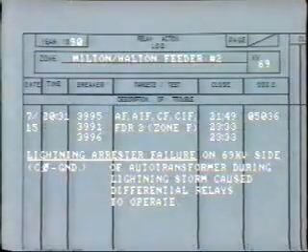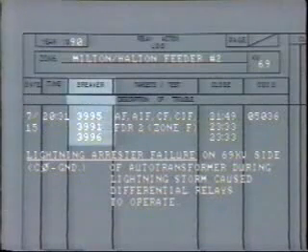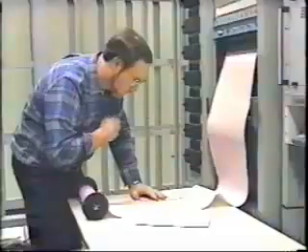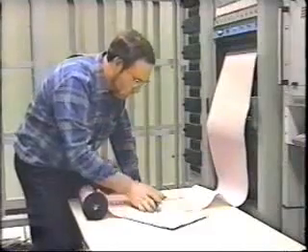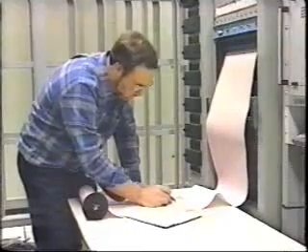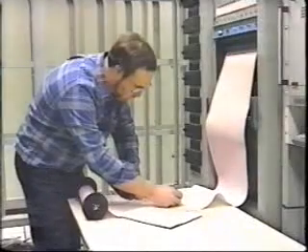The actual information logged includes the date and time of the relay action, the numbers of the breakers involved, the relay targets, the time each breaker was closed, and the number of the pertinent oscillograph recording. In this particular case, the investigator, using all of the data along with the oscillograph traces, decided that all relay and breaker actions were correct.